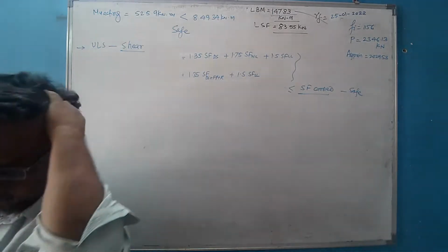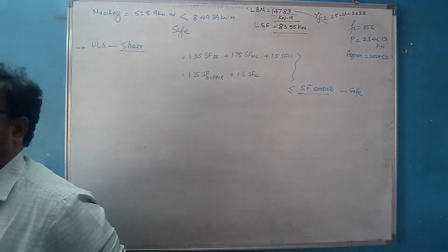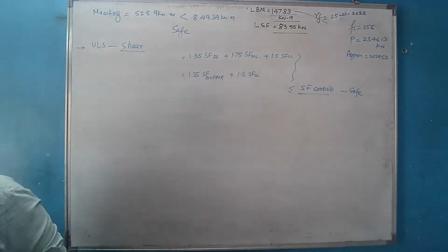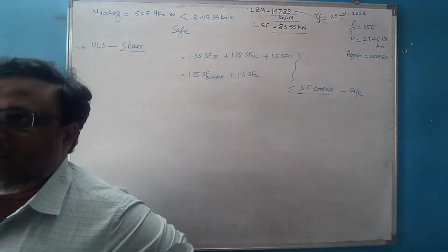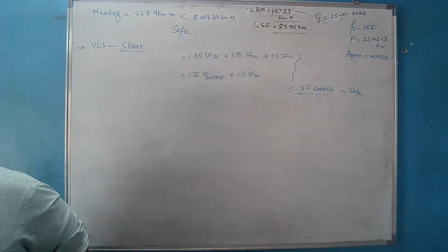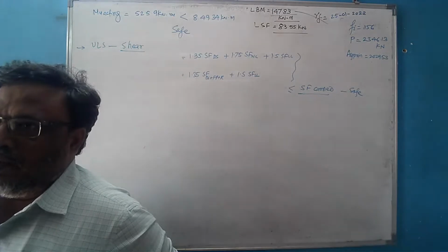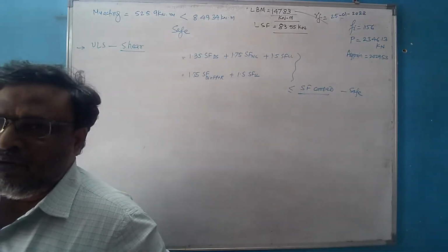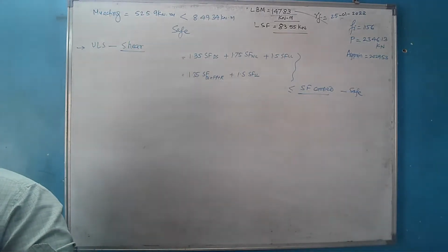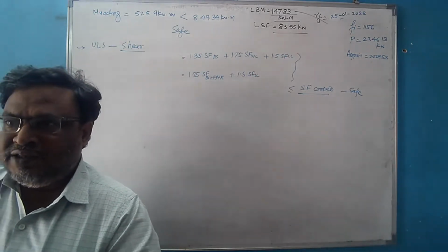So we will continue the same problem that we had left off in the last lecture. If you remember, the problem was to design a pre-stressed concrete post-tension deck slab bridge. The span was given as 9 meter and it was to be designed for IRC AA tracked vehicle. The carriageway width was 7.5 meter, so it was a two-lane bridge. For that two-lane bridge, we had started the analysis.